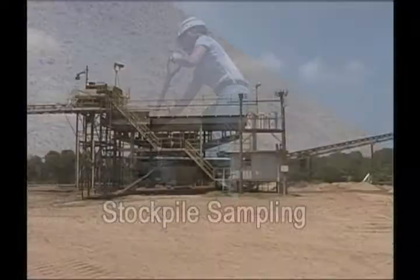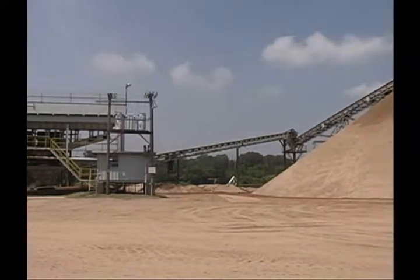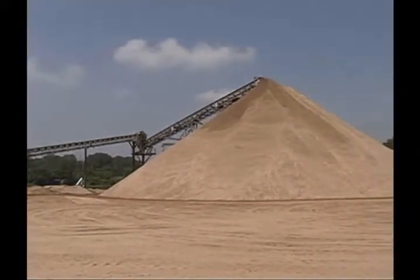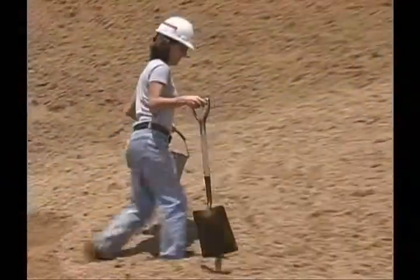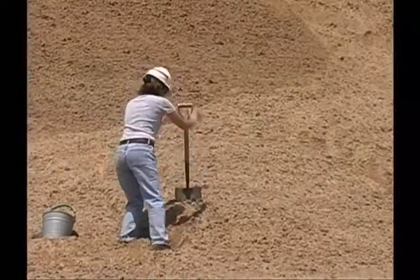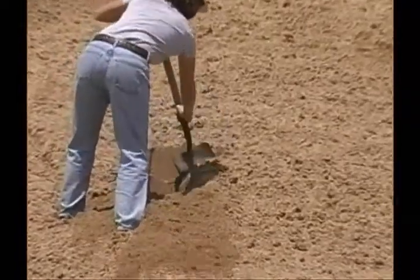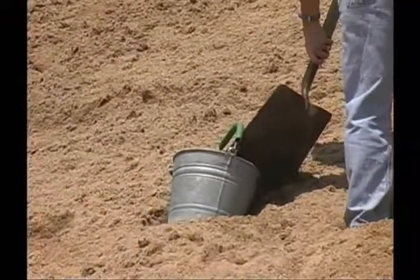Stockpile sampling can only be used for fine aggregate material. This method can be done without interrupting the production process. Even fine aggregate material tends to segregate when stockpiled, so sample the stockpile from 1/2 to 2/3 of the way up the pile. With a square-nosed shovel, cut a vertical face in the stockpile. Scrape the vertical face with the shovel to a depth of 1 to 2 inches